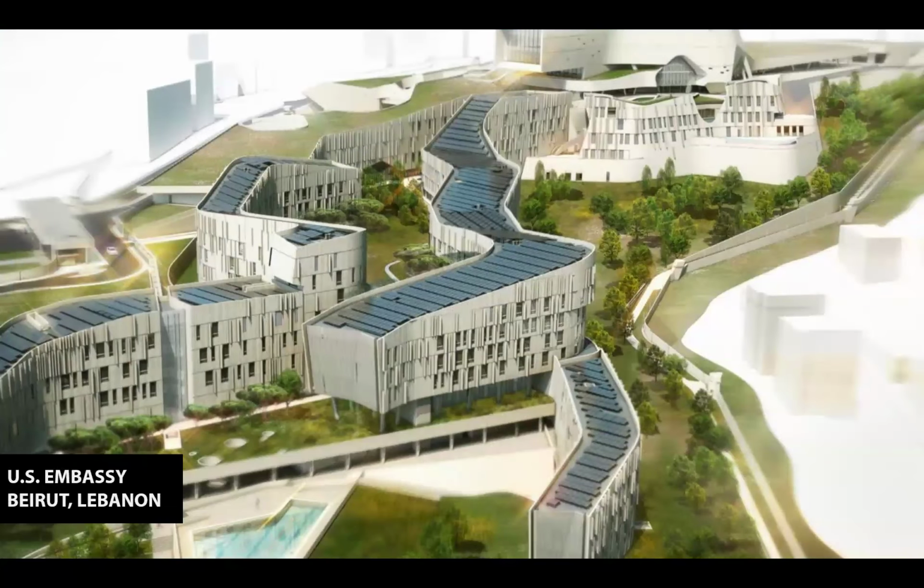No, they do not on the glass side. Glass is essentially one of the most durable exterior envelope products out there in the world. That's why we build our skyscrapers out of it. That's why we utilize it for daylighting, vision, clear lines of sight, but for security as well. So even if you were to get a ballistic or blast rated insulated unit with multiple different layers of solar control in there, you will still get the same life cycle you would get out of a standard IGU as well.